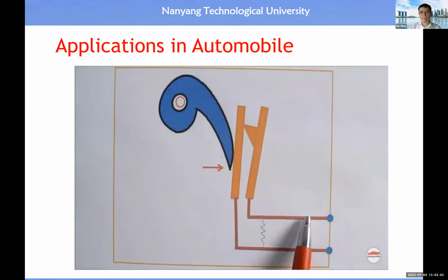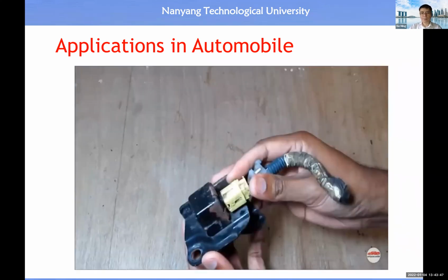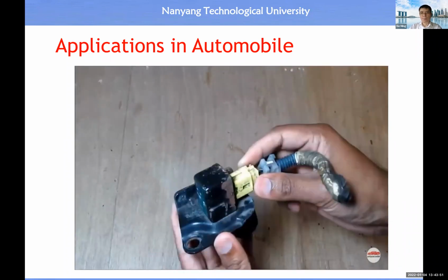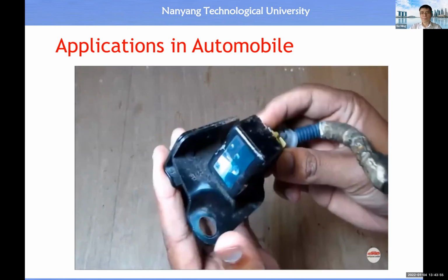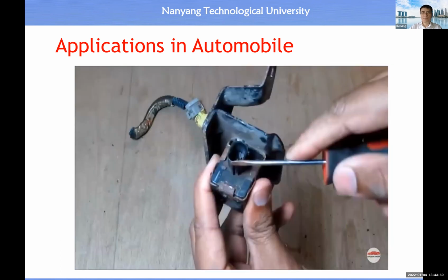This is what the sensor looks like when it's removed from the vehicle. As you can see, rust is probably one of the common reasons why these things fail, because they're located on the front of the vehicle where all the salt and moisture build up. Let's open this guy up to see what's inside. Pry up here. We pull off the connector. Here we've got these metal tabs that hold in the sensor. Just going to pry those over.